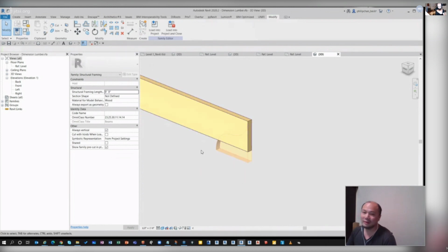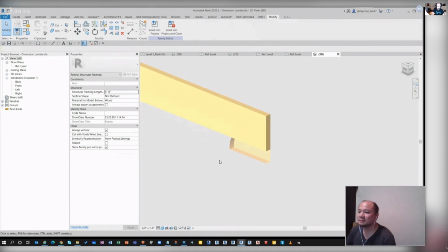No, that's a great tip. I was wondering where you were going with that, but you're right. If you have 17 pieces of geometry and you draw a void, it's going to cut anything it touches, usually when you finish the sketch. Whereas if you only want it to touch one thing, you start as a solid, then you flip it. That's great. That's an awesome tip. Yep.